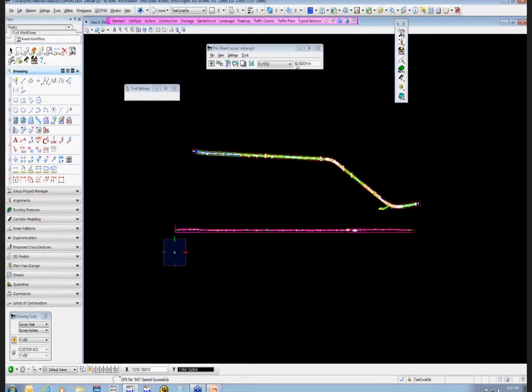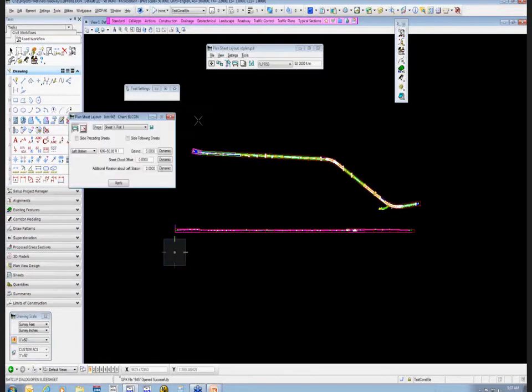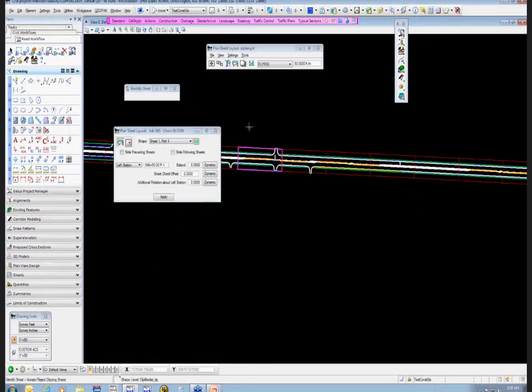Before I clip these, I want to show you a couple of things. Wrong one. Modify. You can modify these borders using MicroStation. It's not always recommended because GEOPAK puts information in here. I've got 2 options. I can slide my sheets, which is just moving them down my alignment, and I've got a couple of different ways I can do that. I can identify which sheet border I want to move, and then I can tell it to slide sheets before it and slide sheets behind it. I could just move the one, or I can tell it to slide everything.